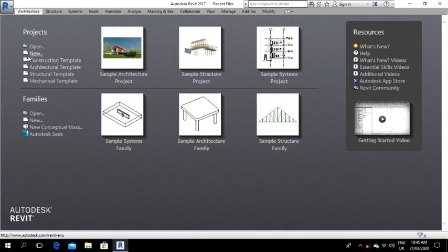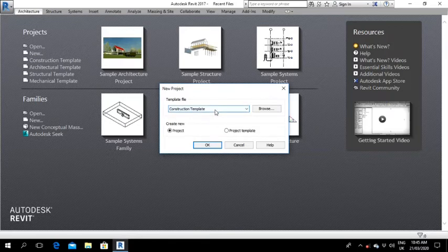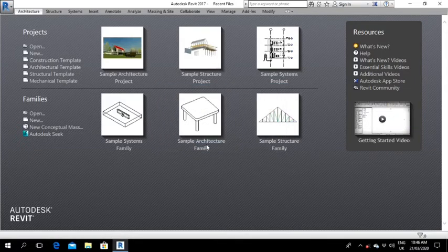In this tutorial, we are going to teach you how to use REVIT architecture. So we'll start by walking you through it. So I'm clicking on new to begin. So when you click new, it brings you to this tab. Okay, the next thing you do is to select architectural template, because that's the one we want to use. Okay, and leave this in as project. The reason is because we are working on projects. Okay, now if you are working on a template or you want to design a template, that's when we select this one. So click OK.